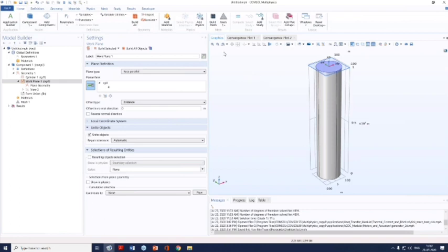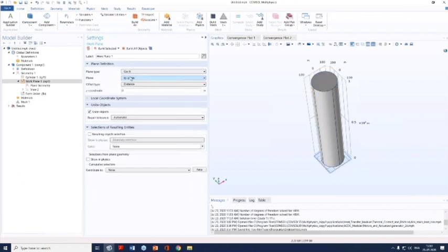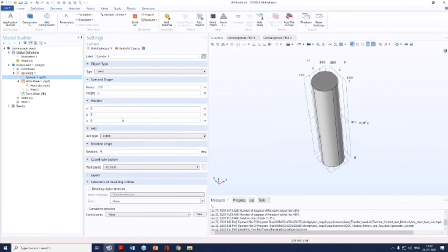And that reference can be obtained if you are using, whenever it is possible, it may not be possible always, but whenever it is possible, you can always use these face parallel work planes in order to create the next geometry. The advantage, as I was saying yesterday also, is that you can use directly just the quick plane which is parallel to xy. But in that case, if I just use this quick plane, you may see that here in this case the cylinder itself is located at 0, 0, 0.